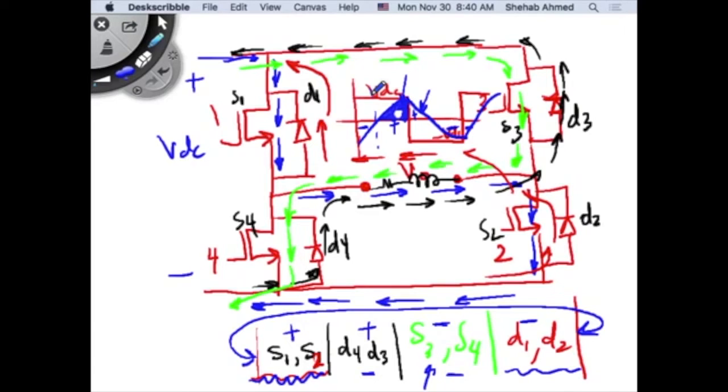Now that you mentioned when you have a larger inductor, just the current ripple will reduce, right? Or will something else change as well? No, but here the inductor is actually your load, right? But in the case of multiple switchings per cycle, yes, it's the current ripple that will change, for sure.